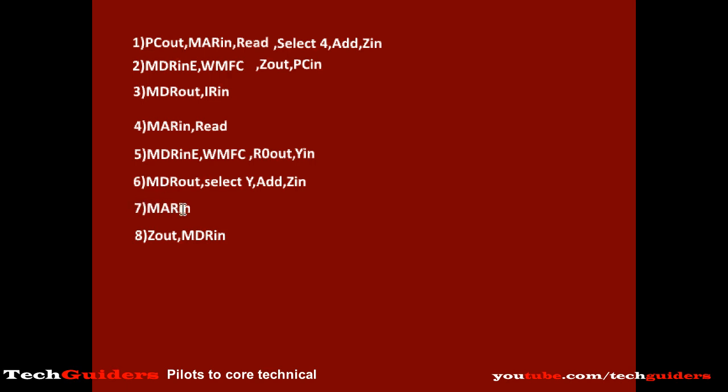The address will be automatically available on the external address bus. From the memory data register, in order to keep the data on the external data bus, we use the MDR out E signal, and accordingly a write control signal will be issued by the control unit, and we will wait for the data to be written to memory, waiting for the MFC signal.